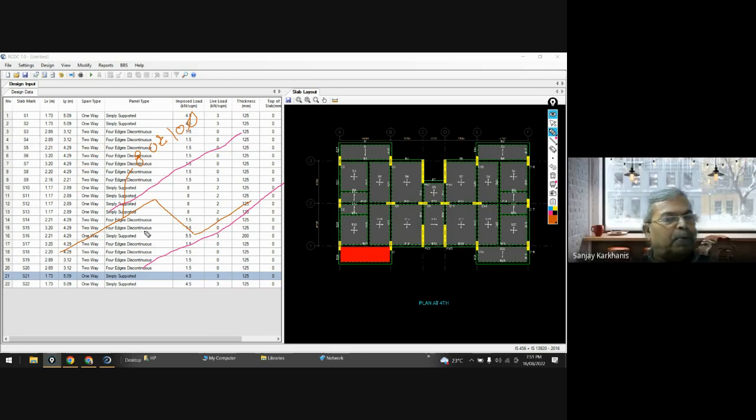So this is very flexible, and when people are walking on this, because this is not concreted, you will have to provide some support to maintain this bar over here. And if the supports are not properly provided, this bar may bend like this.